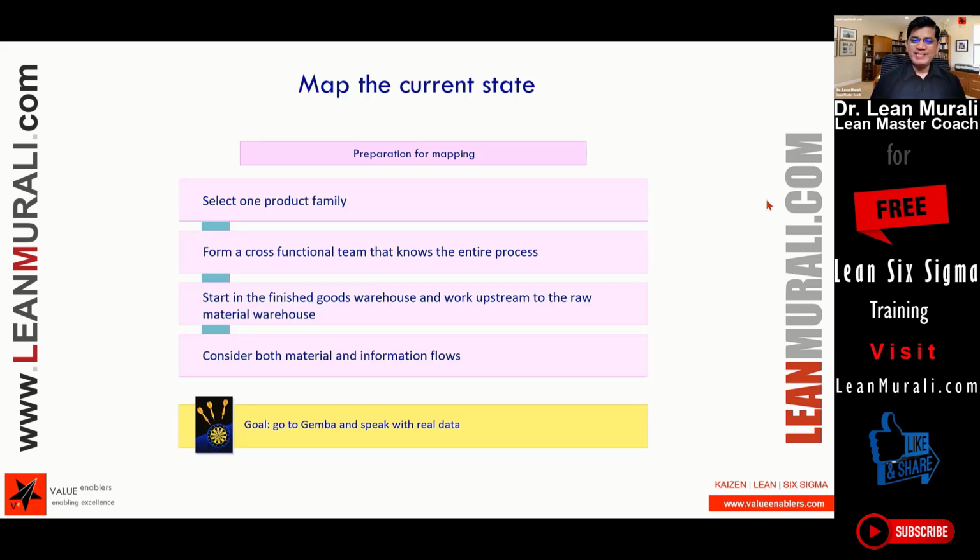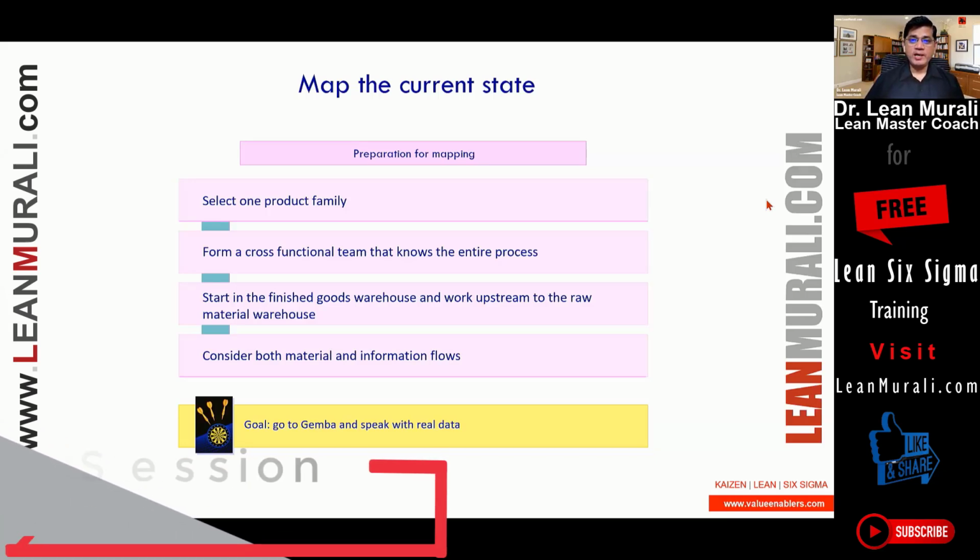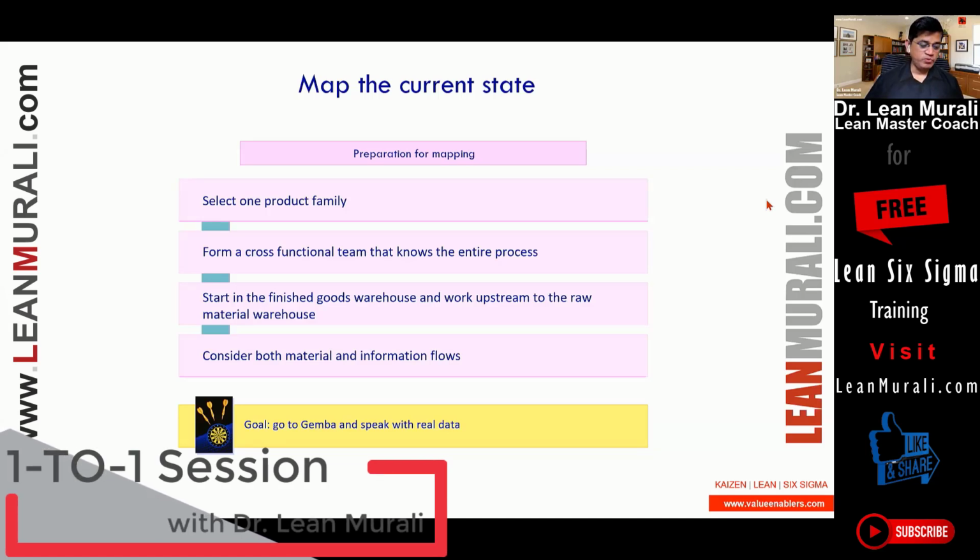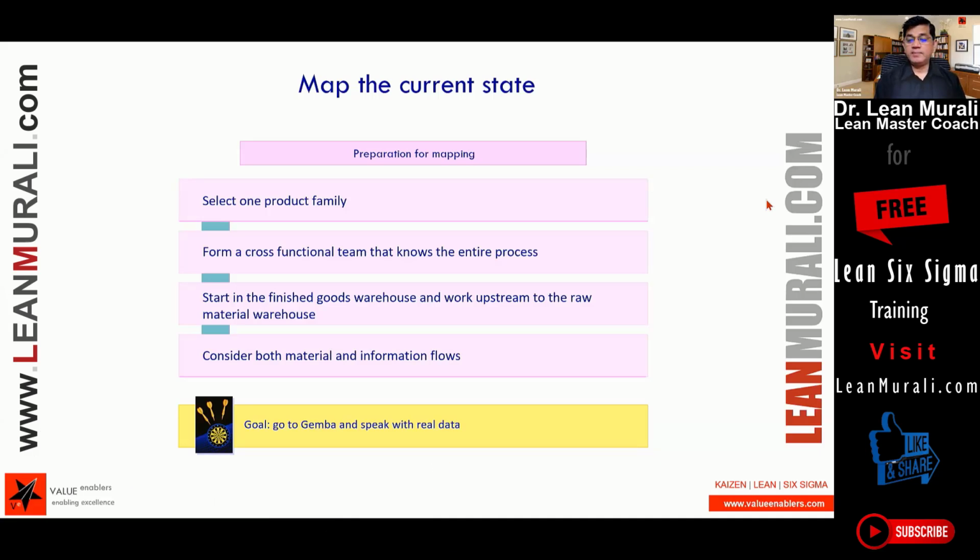Value stream mapping is a snapshot of the process or inventory at that particular point in time, which means you will collect inventory data as a snapshot at the time when we are observing. So it also means that you have to make a call on when you're measuring an inventory as you're walking upstream.